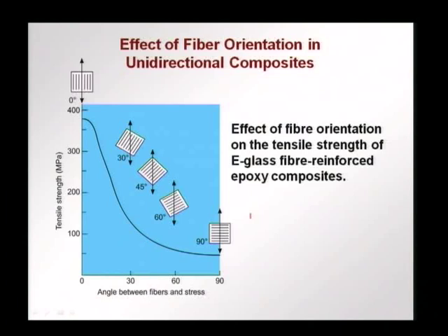So in the application that we are designing, we have to understand which would be the preferential direction of the fibers for that particular application. We have to see where the tensile stresses are coming, what directions they are acting, imagine or decipher from that where the cracks would occur, and use the composite such that the fibers are along the direction such that the tensile stress is resisted and cracks do not open.